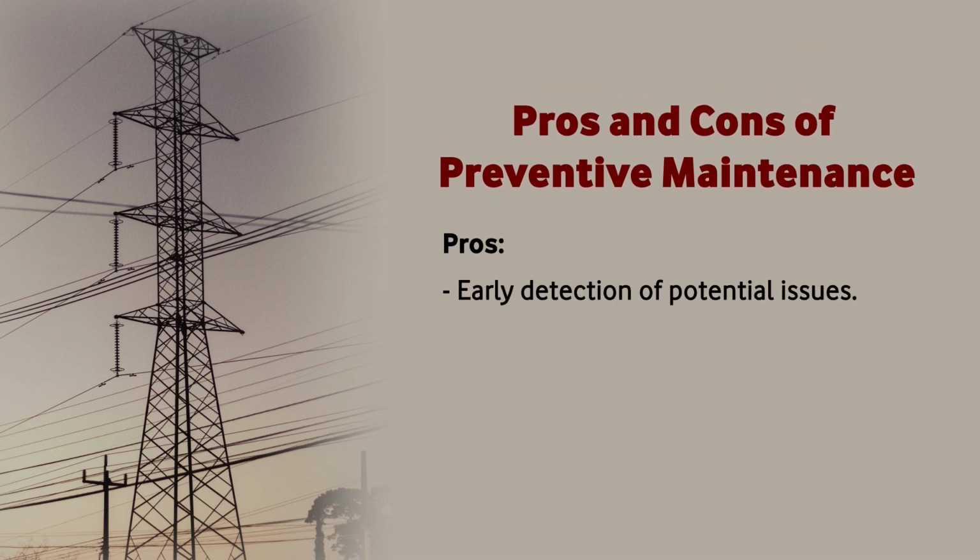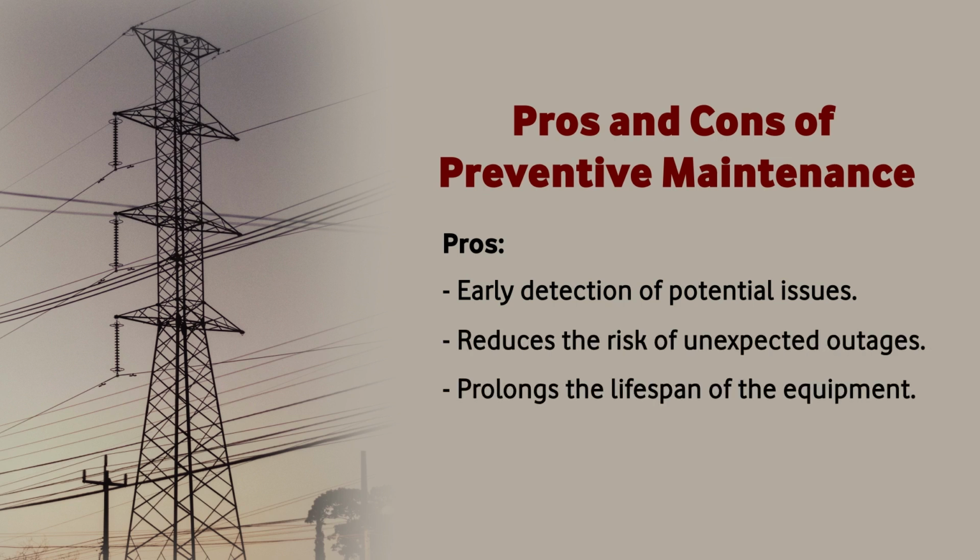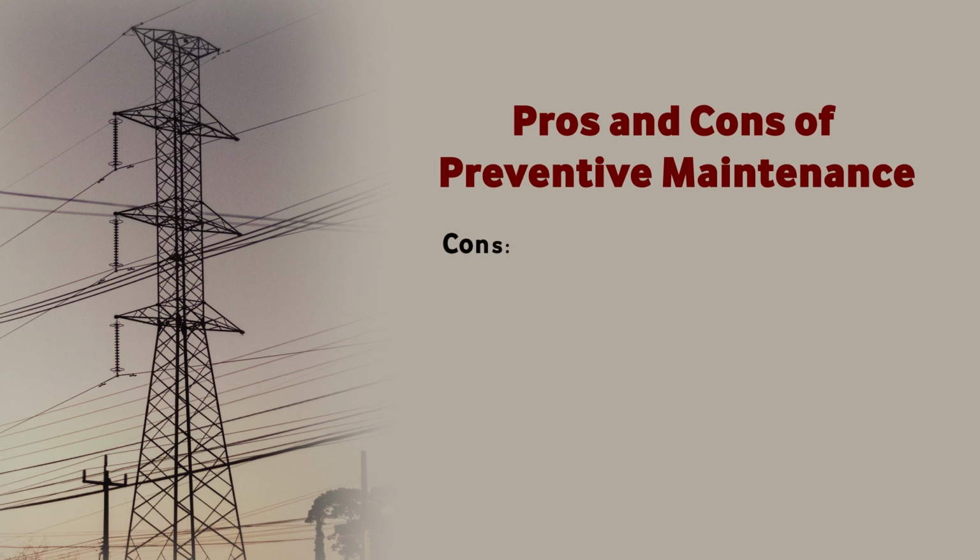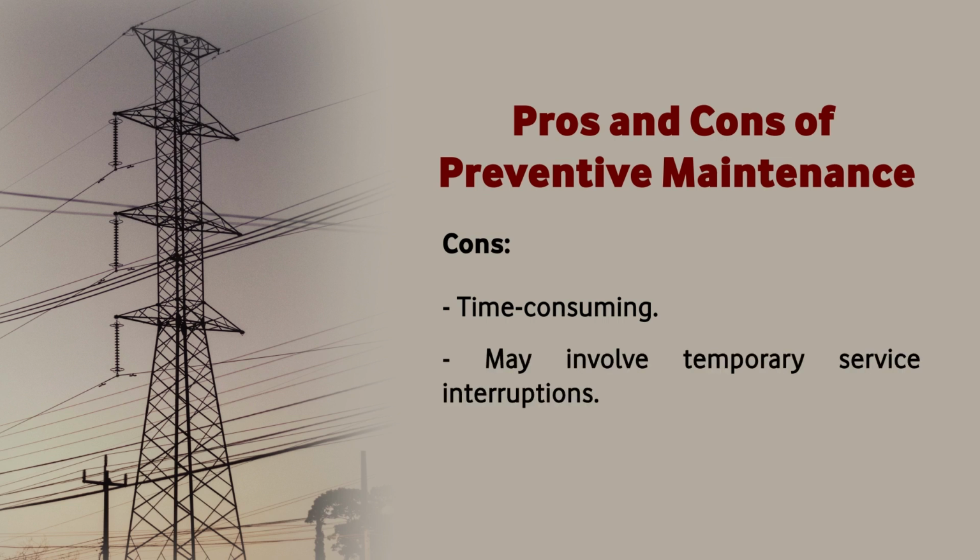So, what are the pros and cons of doing this? The pros include early detection of wear and tear, reduced risk of unexpected outages, and extended lifespan of the equipment. What are the cons? The cons are that it can be time consuming and labor intensive. Sometimes it may require service interruptions.